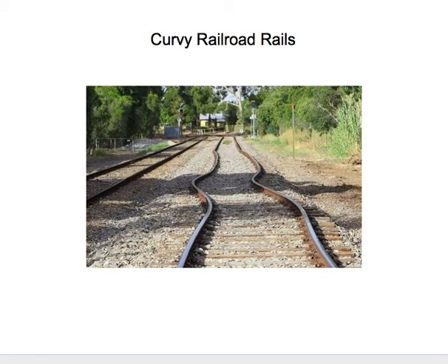What happened is that these rails experienced a fairly large temperature increase, and we see that, let's say from here maybe back to down here at the bottom, those rails tried to expand due to the increased heat, and they had nowhere to go. It developed an axial load in the rail itself due to the thermal strains, therefore giving a thermal stress, and the rails buckled. It's not something you've dealt with before back in 270.